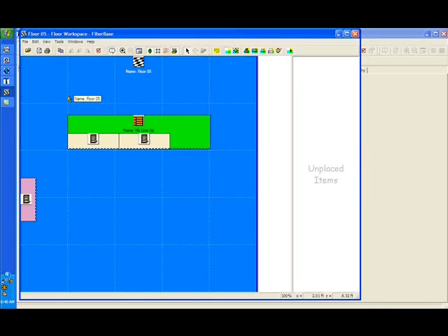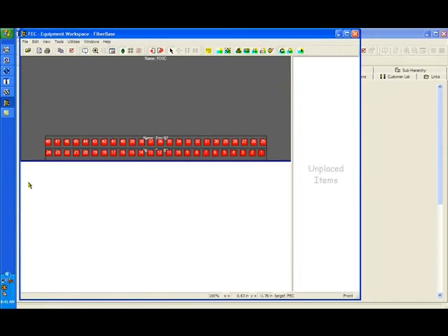The floor workspace is a 2-scale representation. If we look at the bottom right hand side, we can see X equals 11.40 feet, and Z as well, and that will actually move as I move my cursor across the workspace. But here, as we look at these object blocks, I'm hovering over the FEC, or fiber entrance cabinet, and we can double click on it, and that'll take us to the equipment workspace. That'll show us all of the ports in these trays and what is spliced to what.